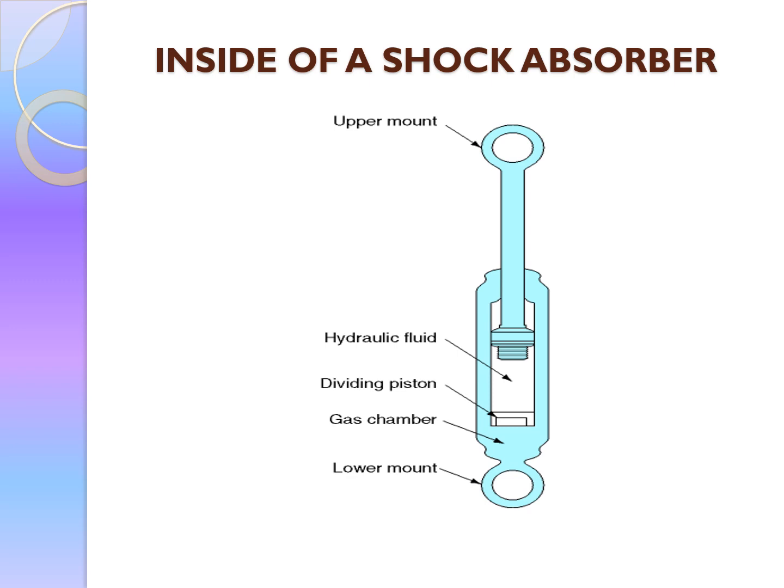A compression intake valve is positioned in the bottom of the cylinder and connected hydraulically to a reserve chamber, also full of hydraulic fluid. The lower mounting is attached to the cylinder tube in which the piston operates. During compression, the movement of the shock absorber causes the piston to move downward with respect to the cylinder tube, transferring fluid from the compression chamber to the rebound chamber. This is accomplished by fluid moving through the outer piston holes and unseating the piston intake valve.